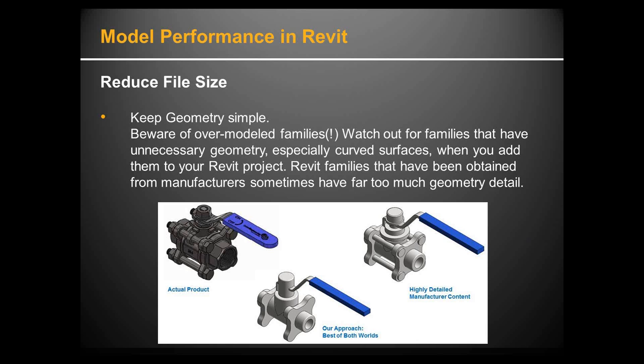If you do have reasonably detailed geometry, maybe use that once in a detailed view or once in the room that you're going to render, and keep a simpler version for the floor plans, for the basic plans, where it gets repeated time after time. This is a huge one, and with a wink and a grin to our friends north of the border who have a famously detailed coffee maker in one of their models.